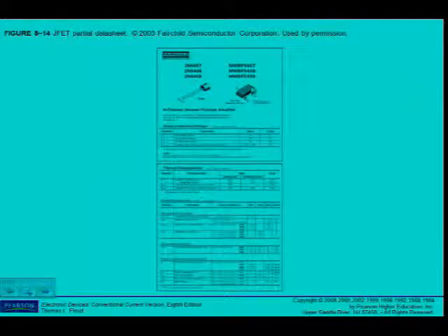For those specific devices. So you'll have to make sure which device you are working with. A bit lower, underneath the on characteristics, there's IDSS for the three different devices, and they give me a minimum, a typical and a maximum value. Can you remember in the example they said typical value?